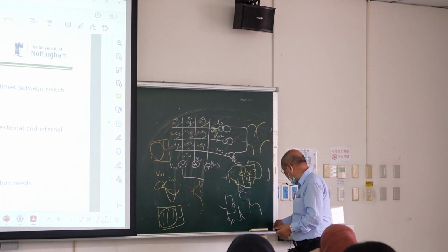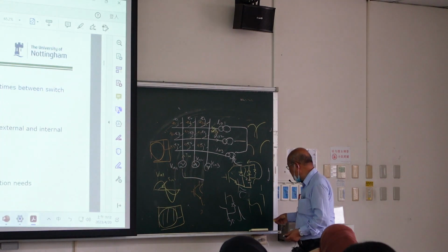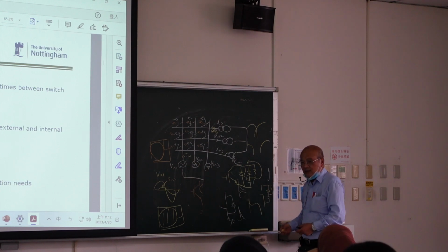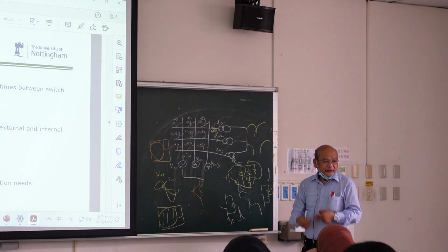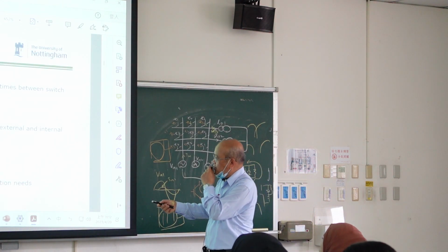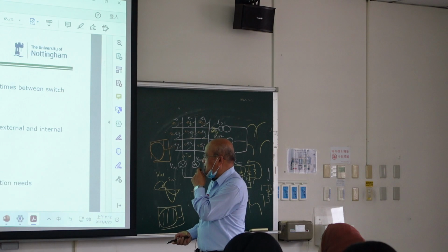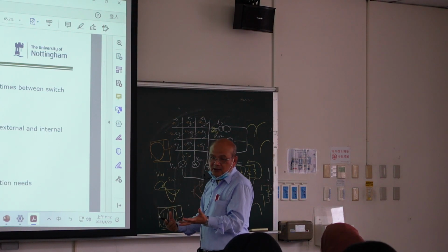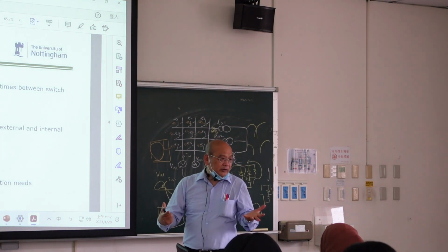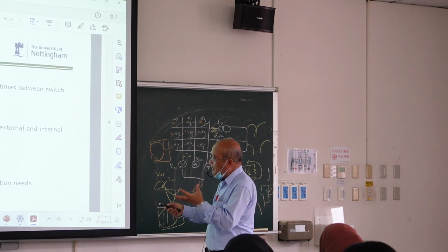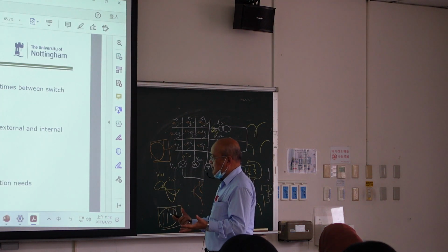But now you have an AC switch. Can you design this for an AC switch? No. So you have no snubber. No snubber. So this is the challenge. If you short circuit, how can you protect? Just burn out. So, short circuit protection. How about open circuit protection?